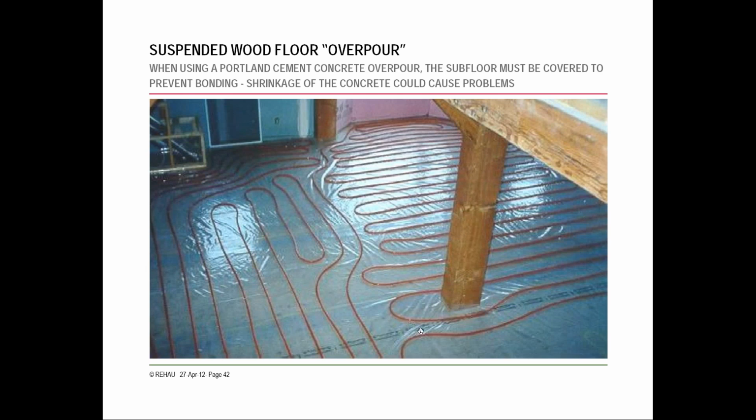Here they've put down a barrier below, as I mentioned, so that they don't have to worry about spraying it with anything. Just make sure you're coordinating with the concrete guy as far as whose responsibility is taking what, or if you're submitting a bid to an owner or a GC, make sure that everyone's coordinating who's responsible for what portions, and then you can relay that to the vendor and to your other subcontractors if needed, directing them who's including what with their proposals.